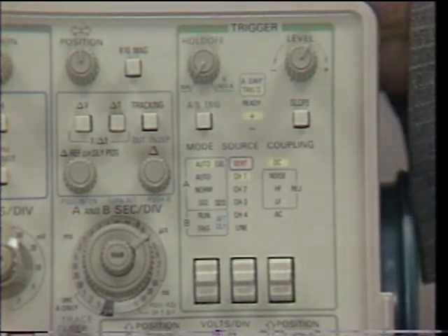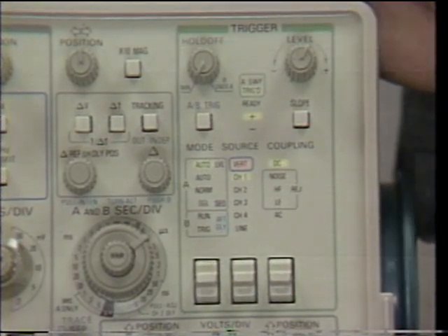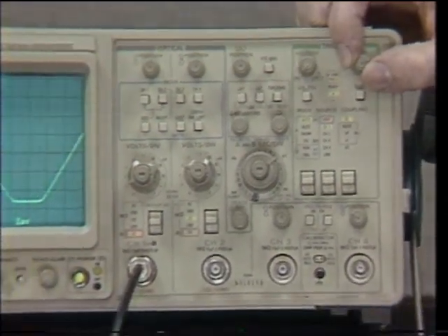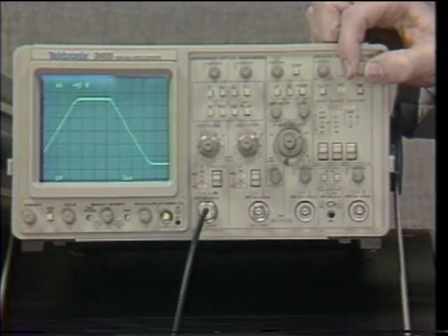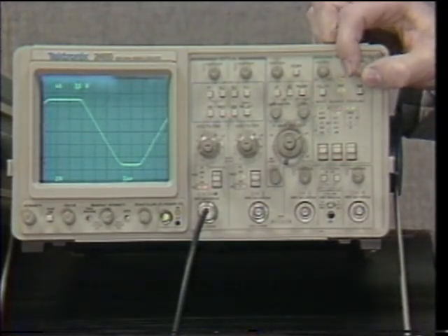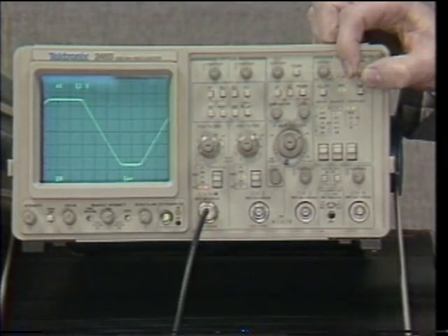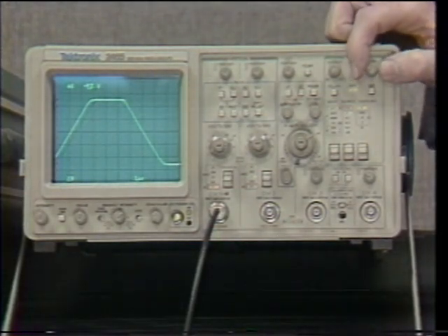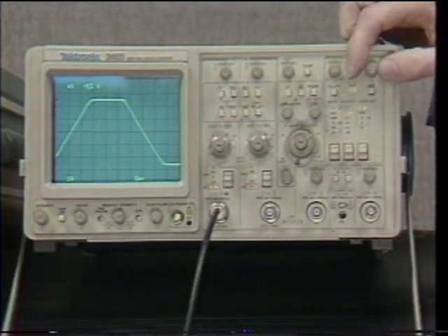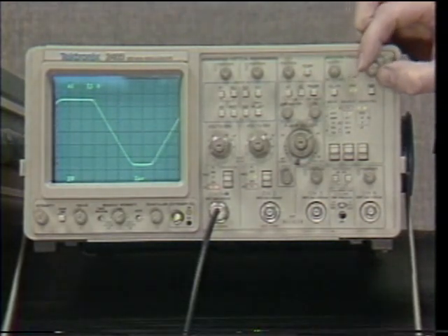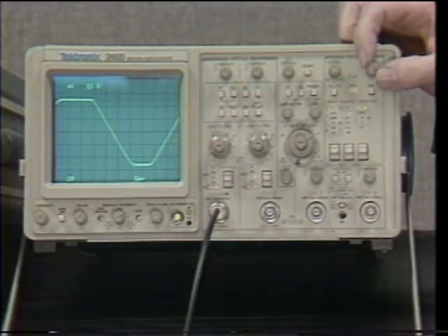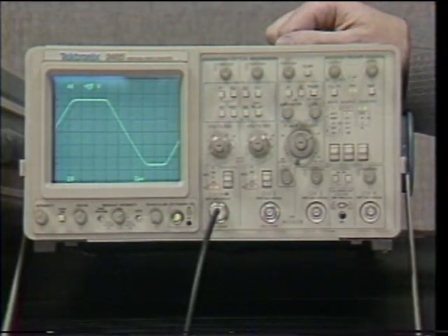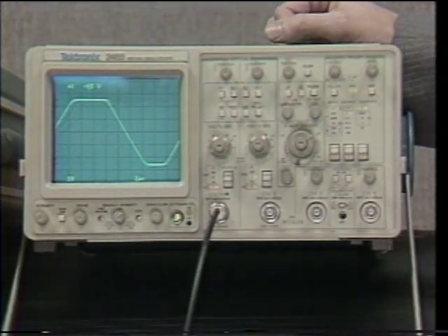Now, the function of the auto level mode is to limit the range of the level control to fit inside the peak-to-peak range of the signal, so that no matter where we set the level control, we will be triggered on the signal. Also, the entire range of the signal will be covered between the fully left horizontal position of the level control and the fully right horizontal position of the level control. Ordinarily, the level control is not needed in auto level. We have a hands-off trigger where the scope sets the level automatically.